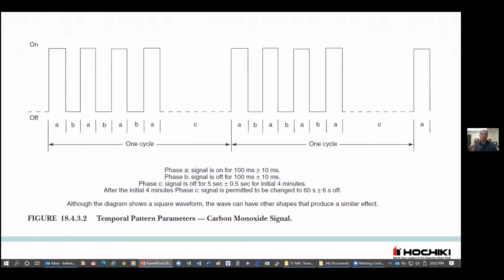So you hear the 4 rapid pulses and then a longer period of time in between. For CO alarms, the residents need to understand that this tone, this signal, indicates CO, and they need to get out of the room and get to a place where there's fresh air. CO poisoning obviously is a problem because carbon monoxide can't be seen, you can't smell it, it has no taste or anything like that. But it will overcome a person if the concentration is high enough, until they become unconscious and possibly even die.